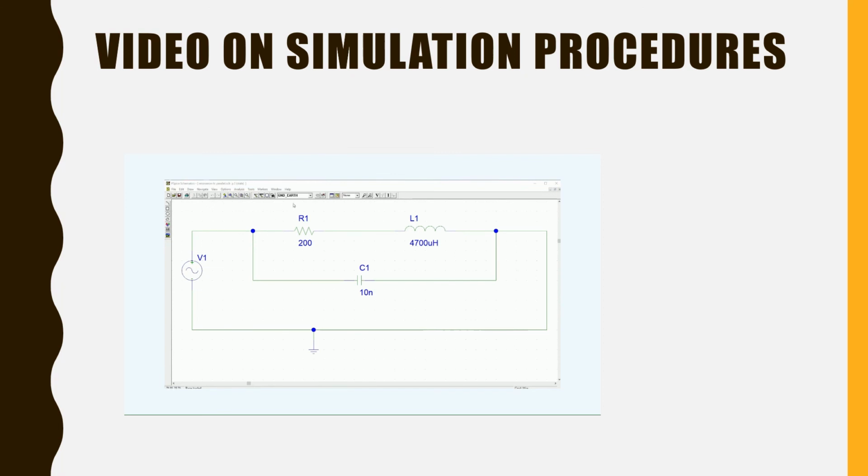After observing the graph for RLC connected in series, now let's observe for RLC connected in parallel. For this, it is the same way of getting the circuit, and the setup here for the voltage source is DC 0 volt, AC 5 volts, V offset 0 volt, V amplitude 5 volts, and frequency 100K.